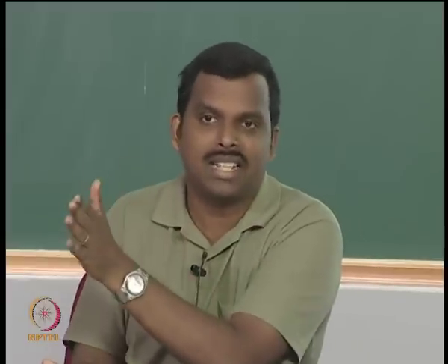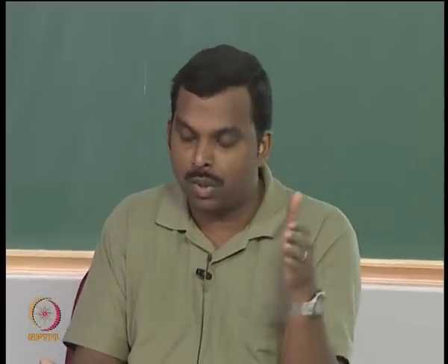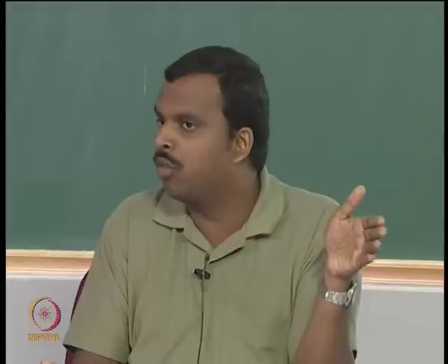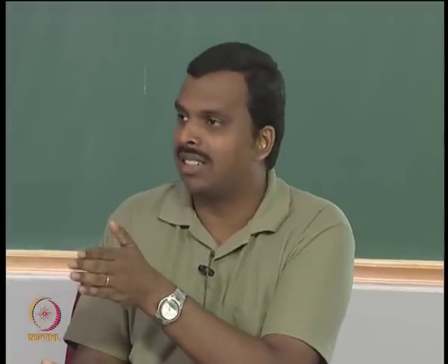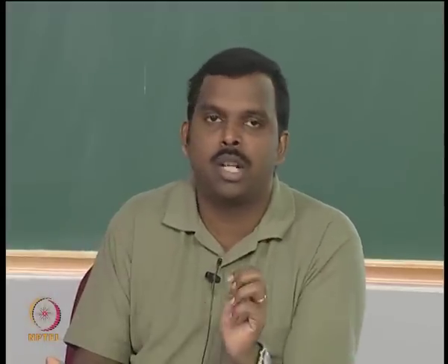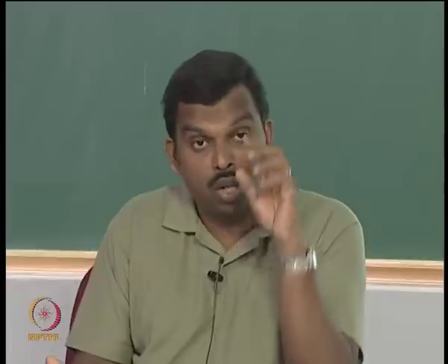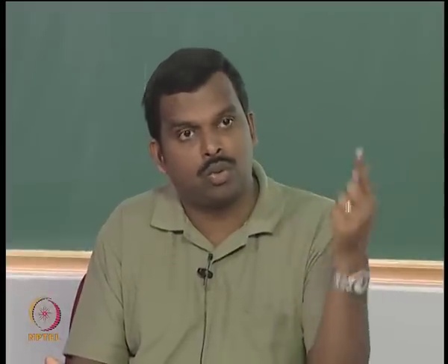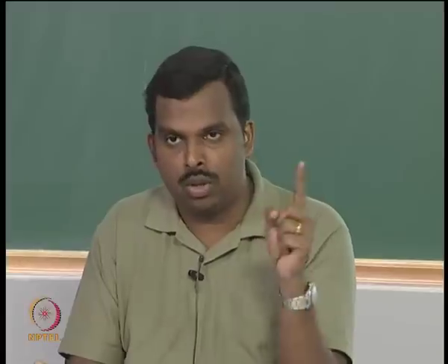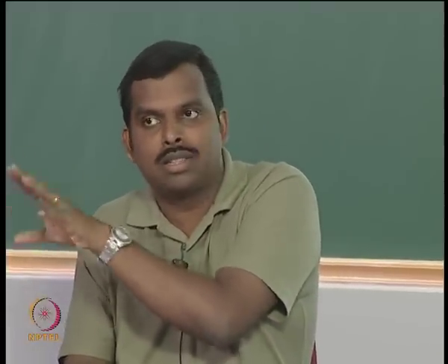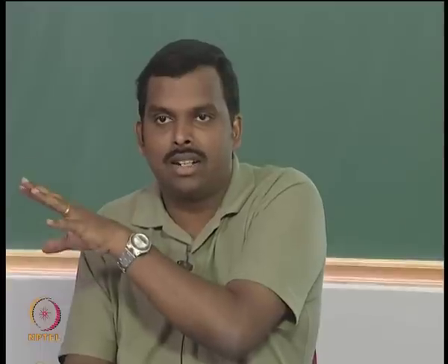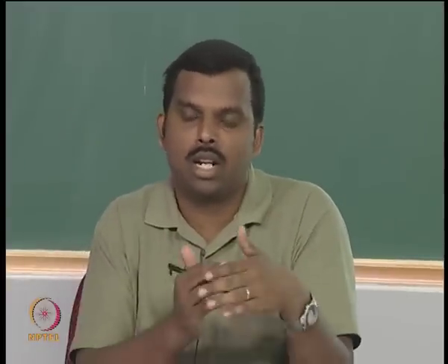When you terminate it dies, but otherwise if you just have an impulse it is technically going to give you an infinite sum, though of course in practice you are going to terminate somewhere. But if you want to think along with the termination, then you have to say that u of D, even though there is a 1 here, is actually a very high degree polynomial because I will put ones somewhere at the end, and that high degree polynomial is getting divided by 1 plus D squared and I will get a lot of ones.